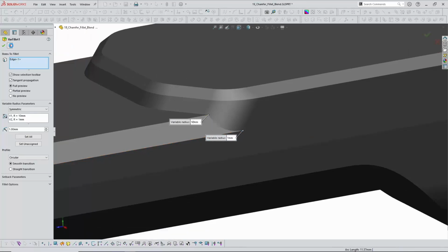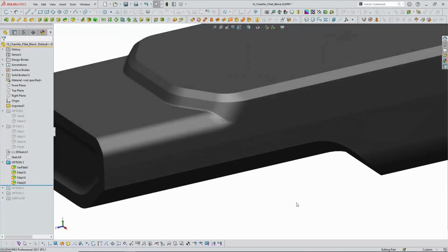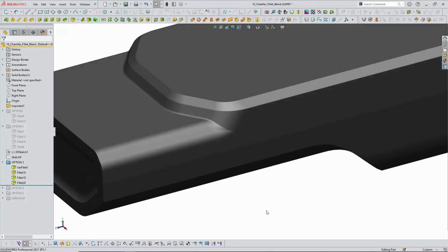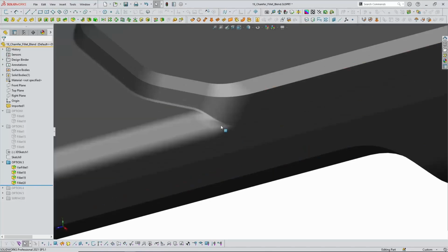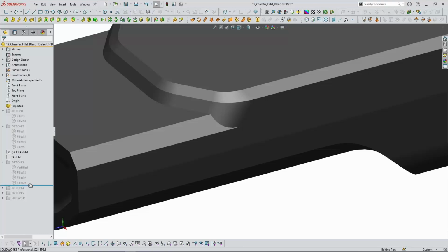It worked a little bit better in this example. And so this was just something that I worked through. I tried a couple different iterations of how to potentially get this blend right. And this blend is looking better, but the primary issue is that this fillet tapers rather than wanting to get larger. And I might have been able to put a variable radius or something on the end, but it wasn't really working.